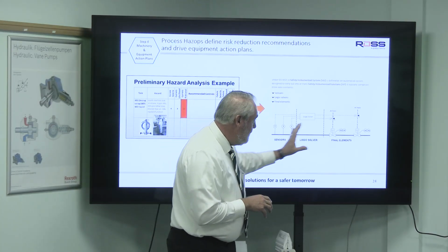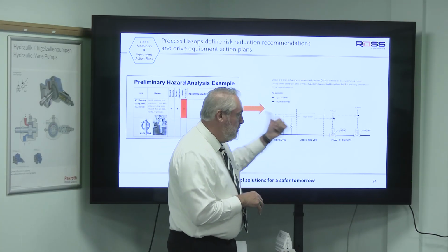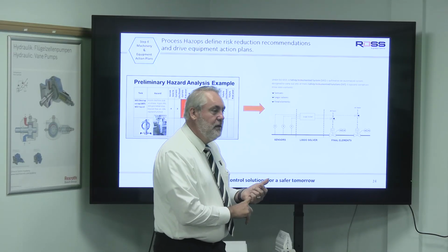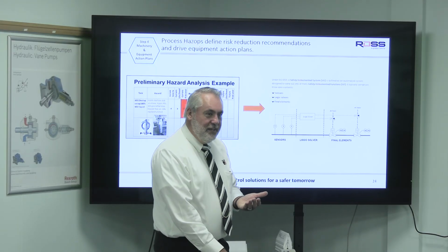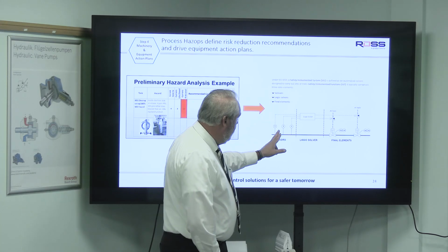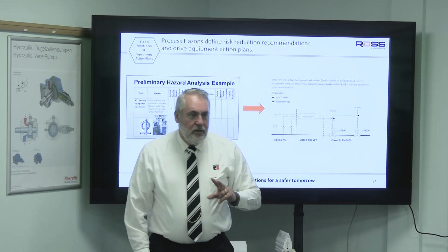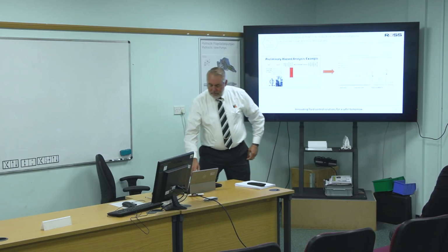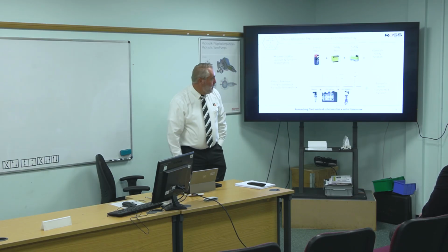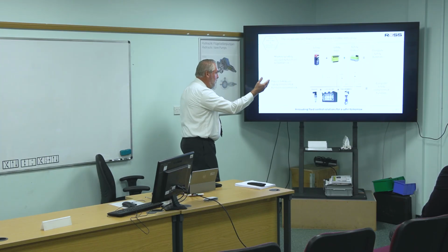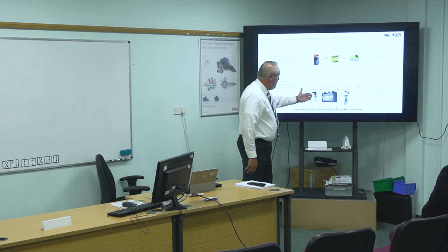So keep in mind, process wants to keep it going. Machine safety wants to shut it down. So any fault in a machine safety system would drive a take it down signal. If one fails here, it gives you an alarm, but the other 2 keep control to keep the process running. So it's a totally different approach. But when we start looking at it, it's all about input, logic, output. And in this case, they've got 3 sensors.